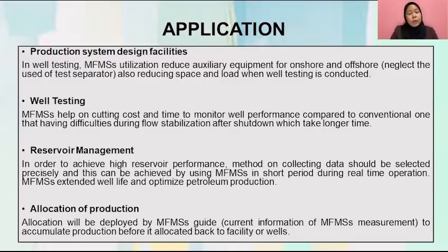And for the second one is well testing. As we know, conventional test separator is very expensive and also requires much time to monitor each well performance. And for that, time required to restabilize flow condition is also longer than usual. Then disadvantages for using test separator is well performance may suffer after shutdown cycle and also require more frequent workover. Thus, by using MFM will give more satisfactory measurement and also can monitor well during clean up flow phases.